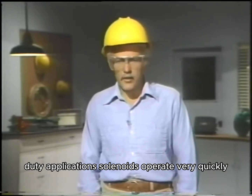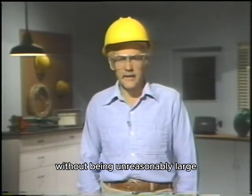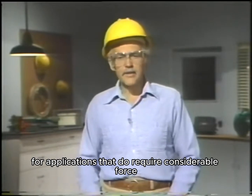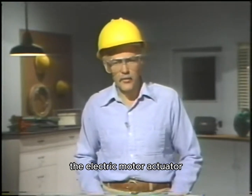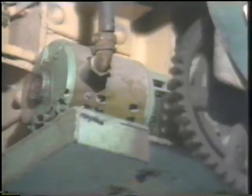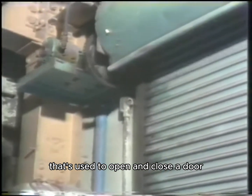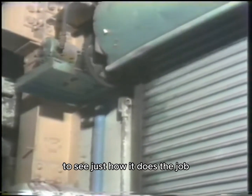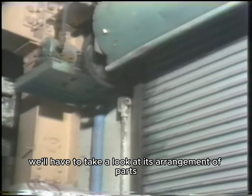Solenoids operate very quickly, but they can't generate a lot of force without being unreasonably large. For applications that do require considerable force and positioning between extremes, another type of electric actuator is typically used, the electric motor actuator. This example shows an electric motor actuator that's used to open and close a door. To see just how it does the job, we'll have to take a look at its arrangement of parts.